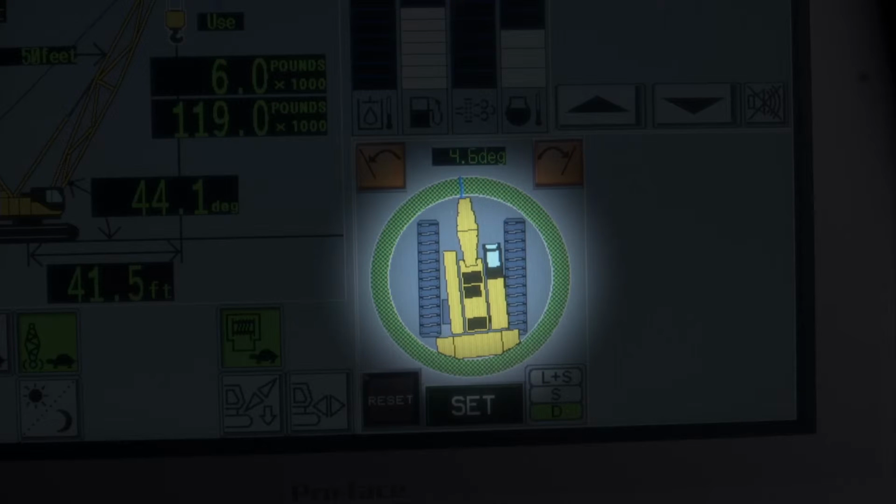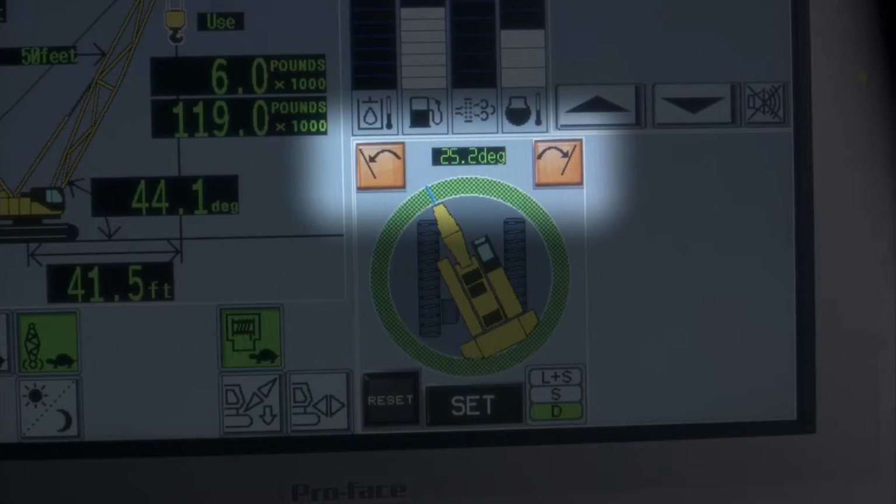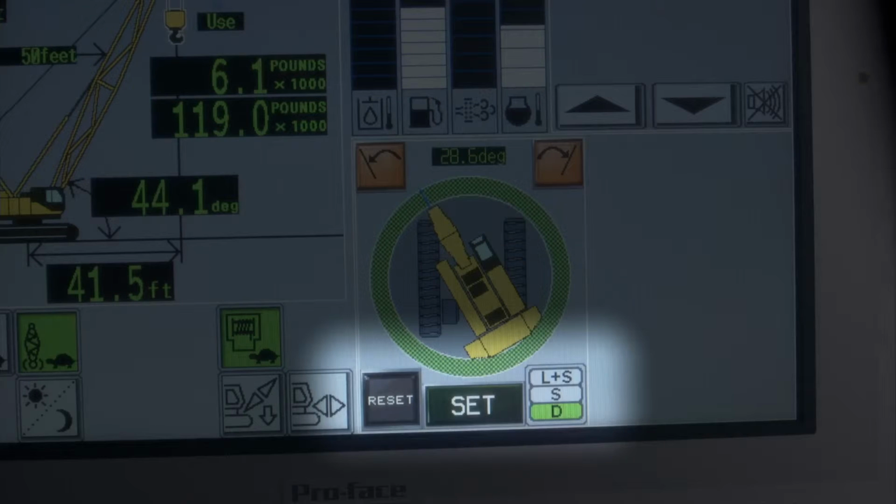The circle is where the operator area limitations have been set. If the circle is green or has small light black shading in it, the circle is just visual. This contains the left stop limit icon, swing angle, and the right stop limit icon at the top. The lower part of this screen contains the mode selection icons for the operator desired modes.